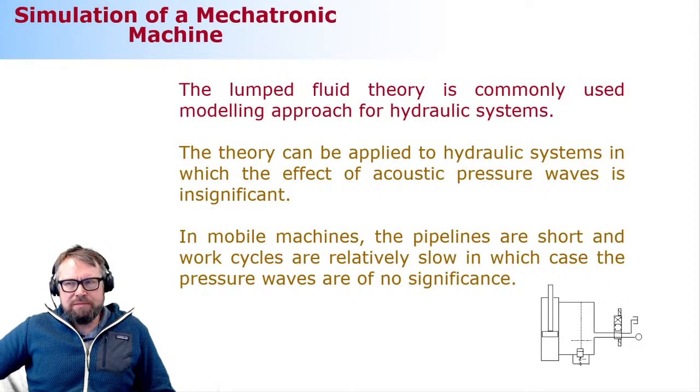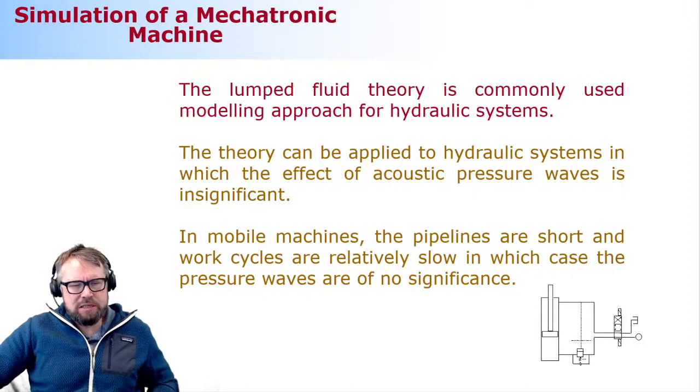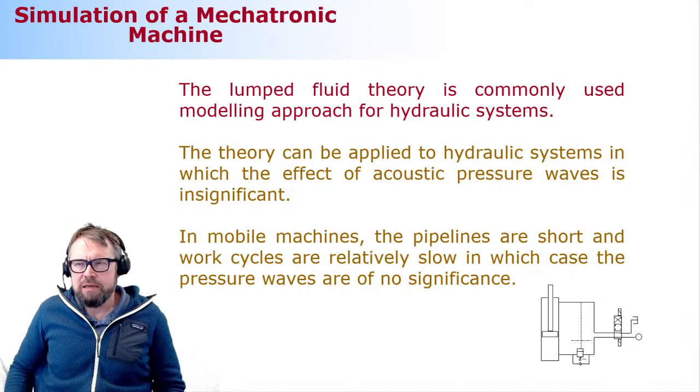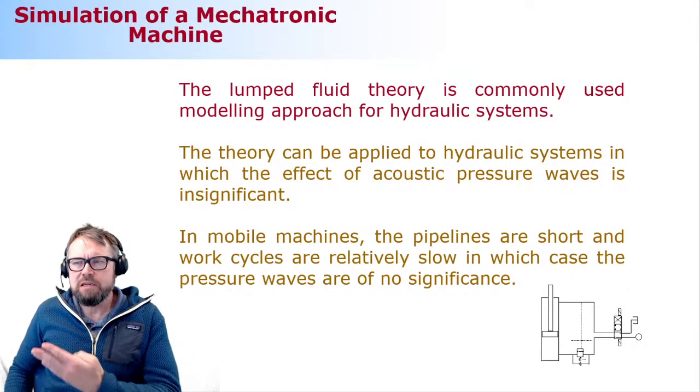Well, here's a little bit of explanation that I have put in writing. This lumped fluid theory is the one used to compute the pressures in different locations of the hydraulic circuit. I first divide my hydraulic circuit into volumes where the pressure is assumed to be equally distributed. I'm going to repeat this in a moment because it is important for you to understand. Then I compute the pressures as a function of time.